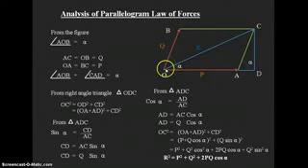So here OC is the diagonal of the parallelogram, so that is equal to the resultant force. So R square is equal to P square plus Q square. Why we got Q square: when you take Q square common from these two terms, we get cos square theta plus sin square theta, which is equal to 1. Like that we got Q square plus the remaining term 2PQ cos alpha.